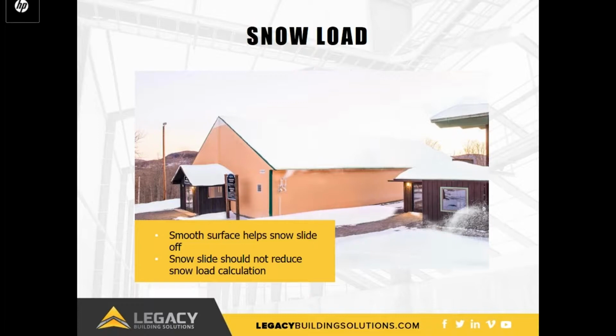In snow locations, Legacy buildings have at least a 2 to 12 roof slope which helps the snow slide off. Some fabric building manufacturers incorporate reductions in roof snow load based on the snow slide characteristics of snow on fabric. However, applying the full snow load requirement as stated in the building code ensures that the building is fully compliant and it provides a high level of safety to the building design.